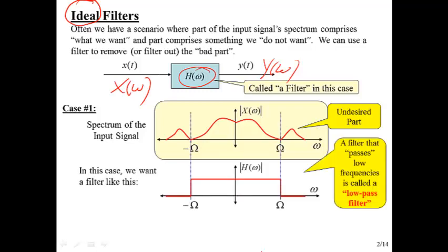Well, it's pretty obvious from this multiplicative viewpoint, and that's the whole beauty of what we've set up here. The whole reason we went through Fourier series and Fourier transforms was so we could get to this point where we say, okay, I know what I want my system to do. I want it to be flat here, and ideally magnitude of 1 there, but it doesn't have to be as long as it's flat. But the important thing is that out here in the bad region, I want it to be 0.